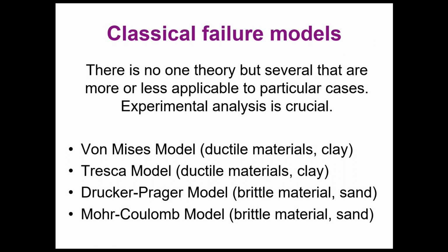When we talk about failure in 3 dimensions, the problem is that it's not easy to see the failure as it is simple to see in a unidimensional test. For example, when you are pulling a bar of steel in the lab and defining a unidimensional test of stresses and strains, it's very simple to associate the stresses, the strains, and the failure, because you can actually see it, and it's very simple to see the failure in a curve when you do the test.